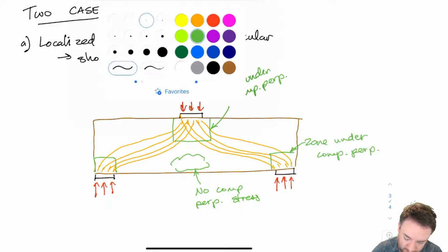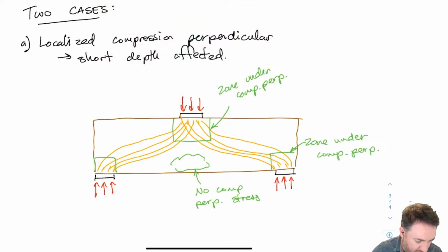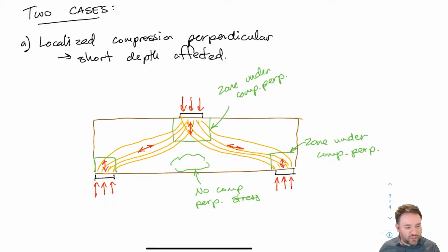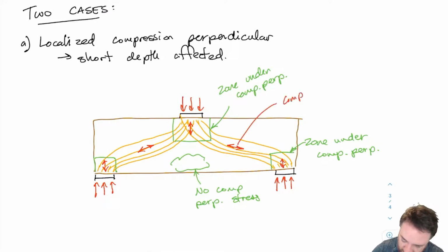Okay, so if we look at the direction of the principal compression at the reaction, it's something like this. In between, it's something like this on an angle. And at the end, it turns again to be vertical, more or less. But that's why we're getting big shears in the beam in between the application of the load and the reaction from the load. So here the compression direction changes.